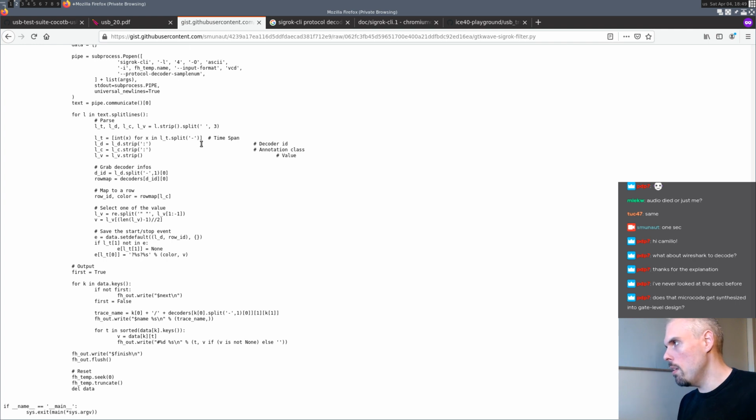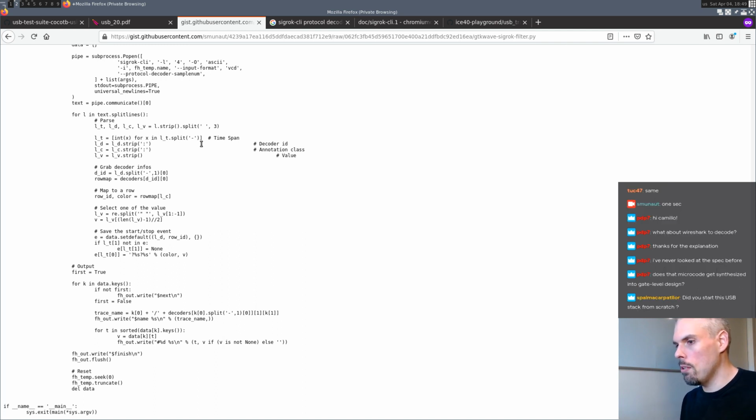The other advantage is if I need my USB core to do something that's not standard, like some weird things, I can just update the microcode, and I can even do that dynamically, because I could make the RAM that contains the microcode writable by a soft core, and so the soft core would be able to patch its own microcode dynamically to generate some weird things.